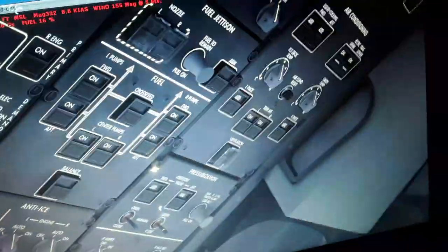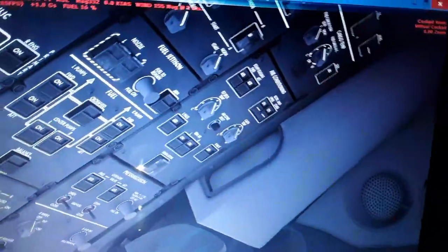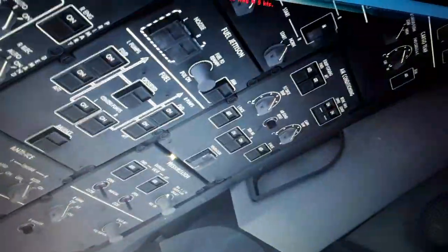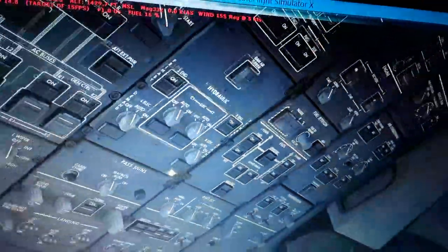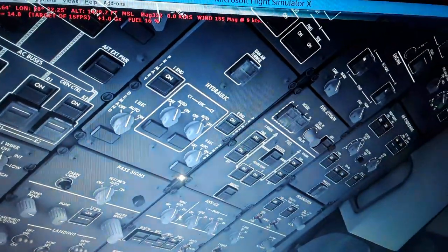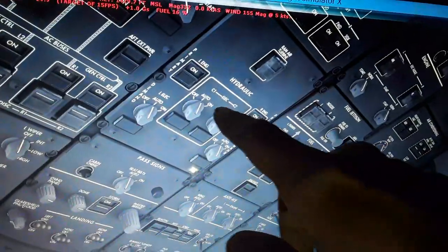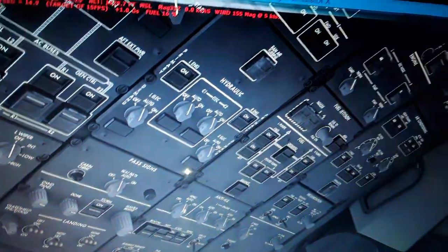So we have the engine's pressurizer, which also supplies the air conditioning, ventilation, and oxygen regulation in the cockpit and the cabin. Also the hydraulic fluid tanks pressurization over here. We have pressurization from the engines for the engine driven and electric primary demand pumps over here.